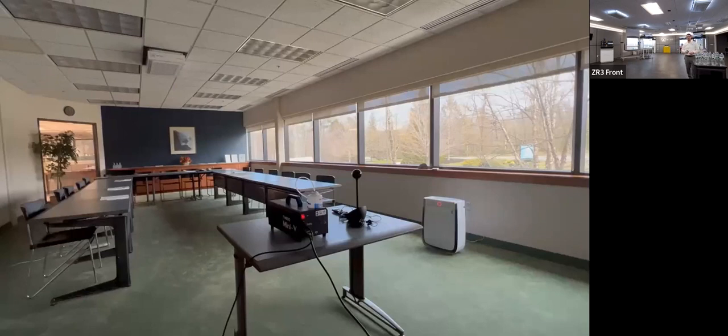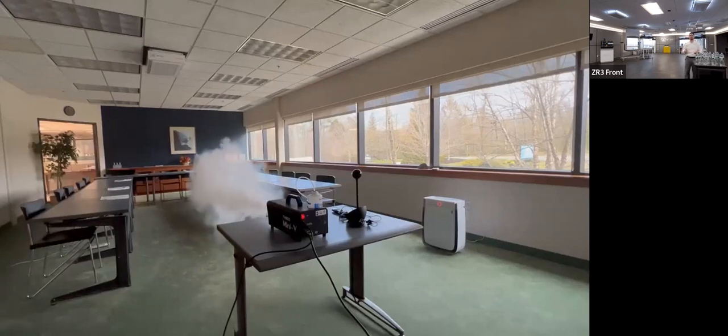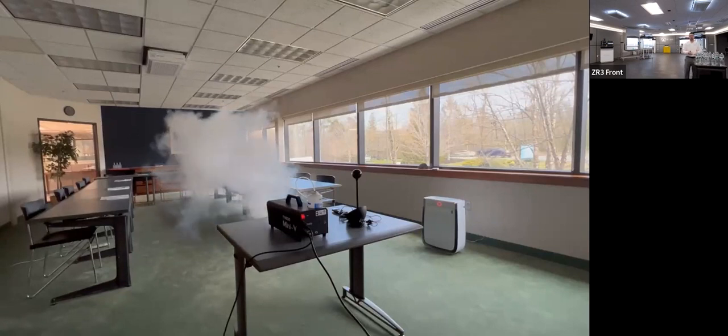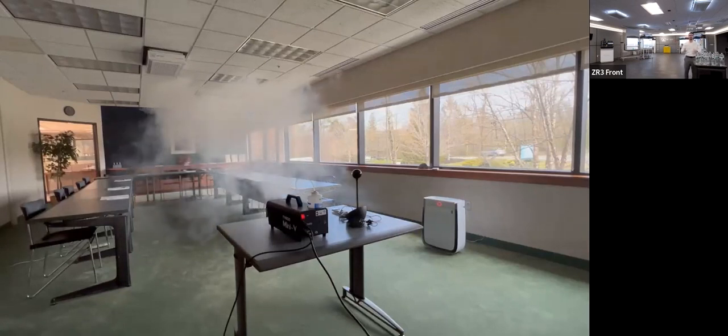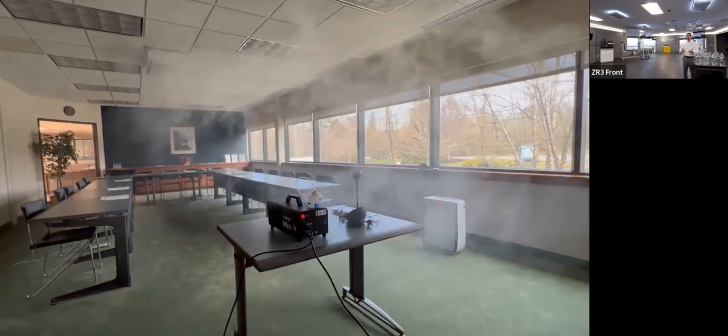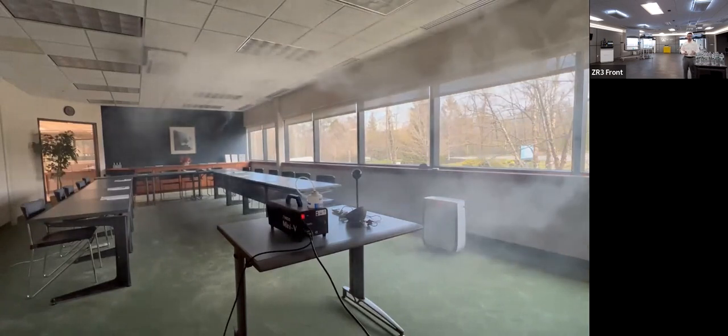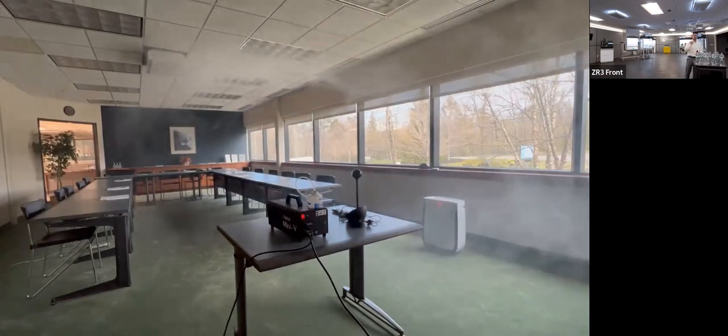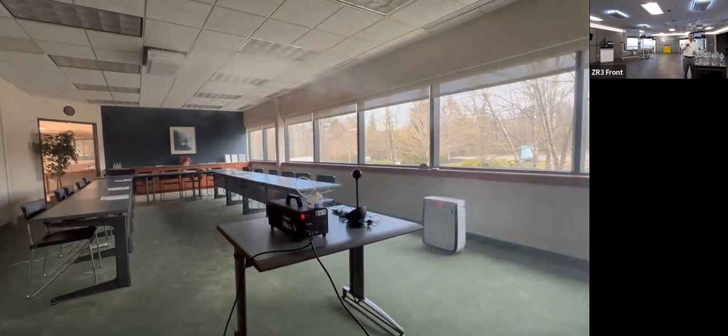Now this system's on over here. I'm going to start the video, and we released smoke, and we wanted to see how this works. Do we drive these particles? Let's just pretend this is a bunch of viral particles. Somebody just sneezed. How do these systems work? Well, you can see here, ventilation effectiveness is extremely poor. And it's literally bringing that high concentration load right to the breathing zone of the people in back of the person that sneezed or who's infected. And it's just not doing anything. You can see the smoke up above. You can see it all lingering for the person that's behind that infected individual.